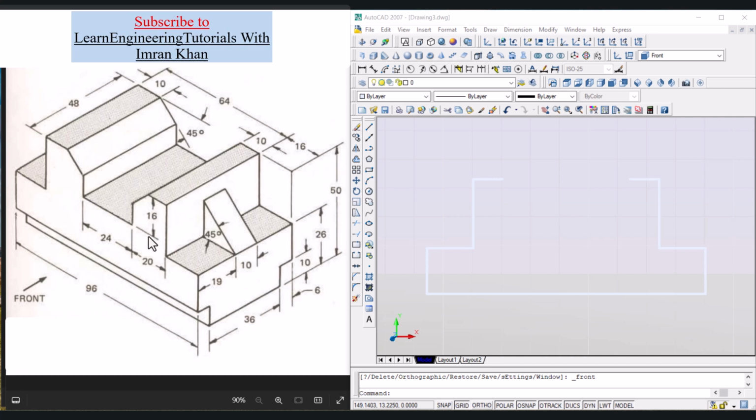Now we have to draw this 24 mm line at the middle of this object at a depth of 16 mm below this upper point. So click on line, click on this point, bring the cursor in the negative y direction and write the value of 16, enter.